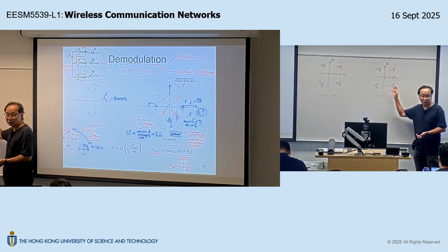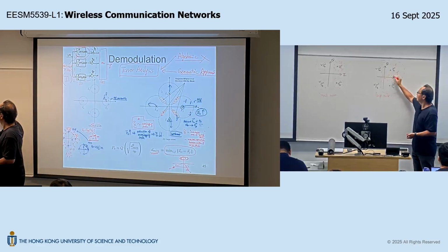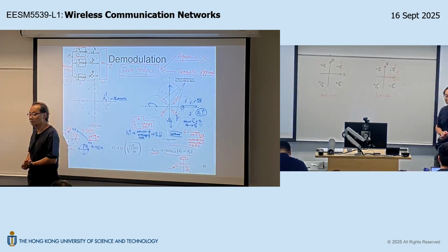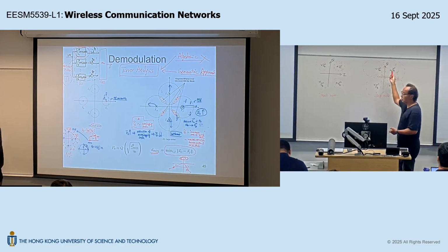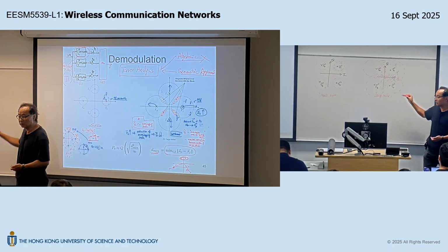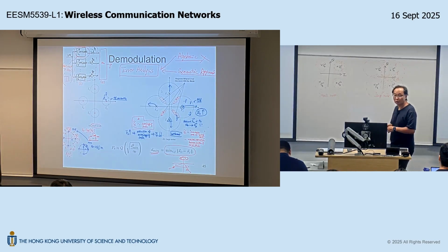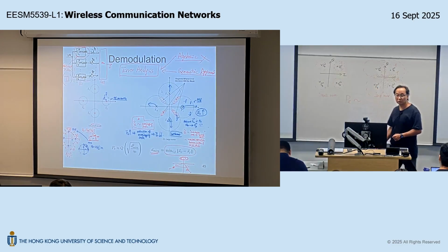Now, can you visualize the error mechanism? Error will occur whenever you are in the overlapping region between the noise clouds. Can you see that? Likewise, you can extend the analysis to consider the noise cloud about S3 and the noise cloud about S4. So all the overlapping area between the noise clouds would be the dangerous area. When your observation lies within this overlapping area, you will make a mistake. Is that okay? So, therefore, geometrically, the error probability is related to the